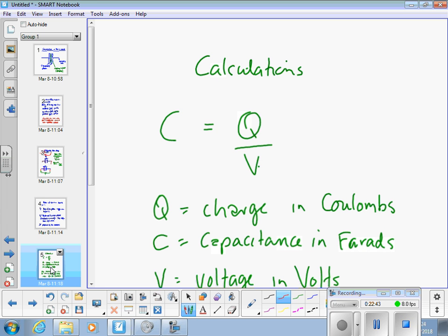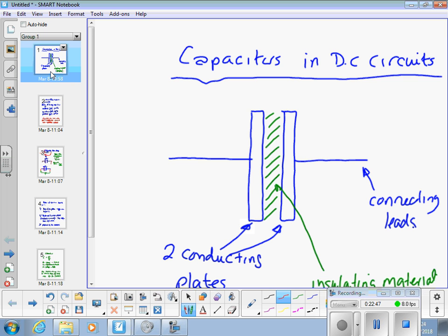What happens when we go over the working voltage? Well, a capacitor is two plates insulated by a dielectric. This is an insulating barrier, but everything has limits. If we push hard enough, it will break. A paper capacitor will blow the can and spread paper everywhere.